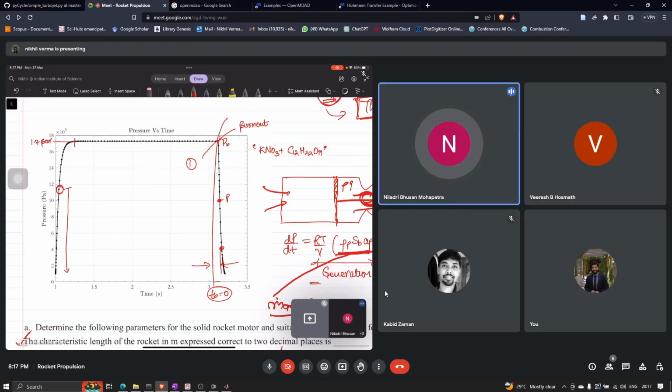No, I think you didn't get it. When I am opening my valve, it will take some time for the valve to be fully open. Initially, from 0 to 100% opening, the mass flow will go according to the amount of orifice opened. Right. So with the m dot, what I am taking now is a constant value. Can I write it as a function of how the valve is opening, so that it can give a better result?